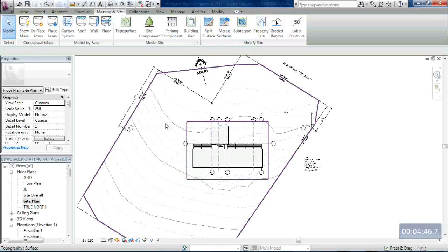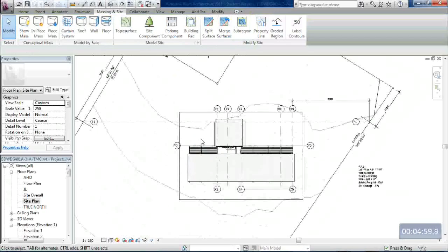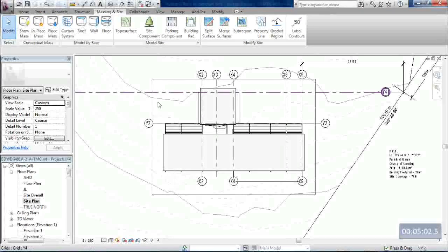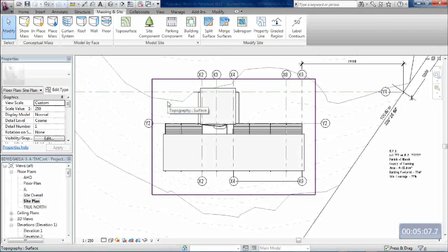In actual fact, this top line through here is a single value contour that I've put in separately. It's the level that I've predetermined that you want for this platform in here when we level out the soil. In this particular case, I decided to use 409.9 metres. So I have the 409 metre contour here, 409.25, 409.5, 409.75, and then there's an extra 409.9 metre contour before we get to 410.